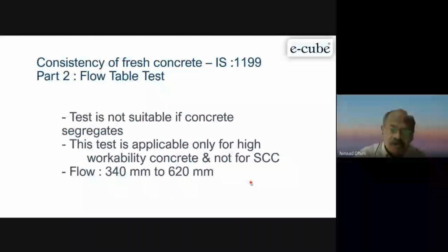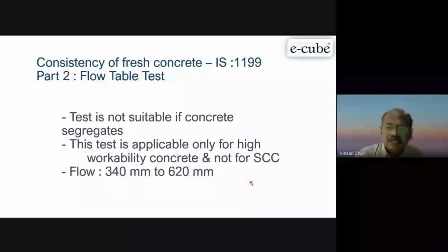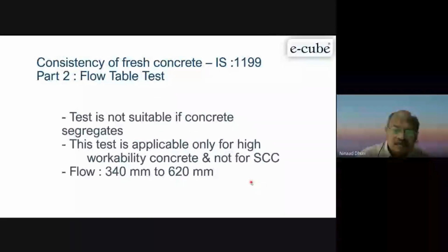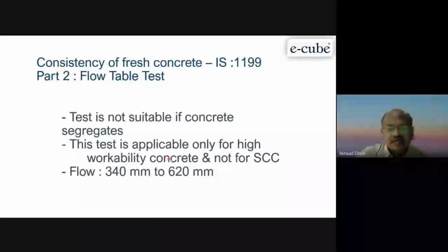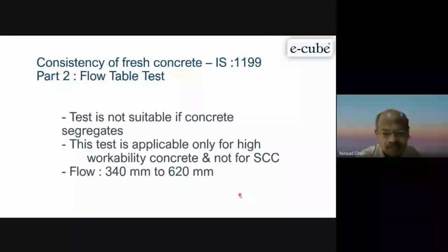So we have flowable concrete, but it requires vibration. For that, this test is there. And this is very important nowadays. The way we are doing concreting at project sites, most of the concrete we do is flowable concrete. So there is a term people are using, free flow concrete. There is no free flow concrete.